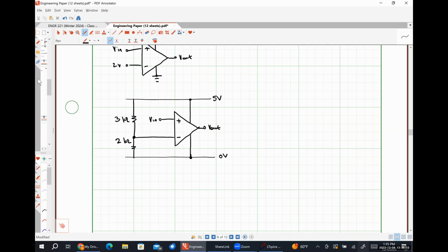What are you trying to solve for? Trying to solve the high one. So I1 is equal to 0.1 IY, and then IY is I2 minus I3. Then you'll do a KVL equation on this one, a KVL equation on that one. And that's not your Norton current, that is your test current. That's correct, but that's just going to be negative I3.